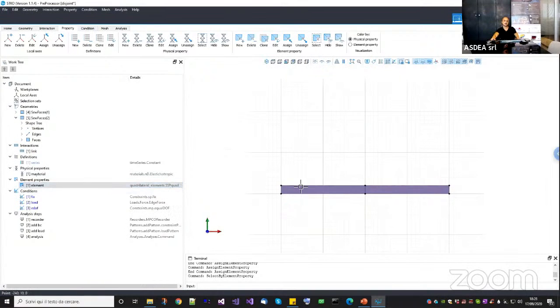Why? Because basically now, assigning an element property to the edge of this face explicitly, I'm telling STKO that here I want to use this edge, not because it is a boundary of the face element, but because it needs to be another element. So I'm explicitly telling STKO to generate an OpenSees element from that. And this element should be an SSP quad. Now, of course, this is a mistake because in STKO, this one is a line element. So I cannot assign an SSP quad to a line element.